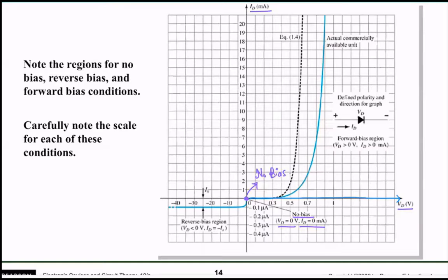What happens is, because your diode is made up of a semiconductor material, say it is made of germanium, germanium has a potential drop of 0.3 volts. What does that mean? Say at the input you are getting 5 volts, at the output you will get 5 minus 0.3, 4.7 volts.